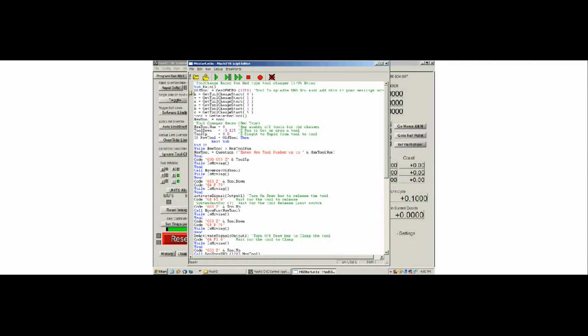As soon as that arrow goes past it, I can cursor over it, and old tool equals 4, so we know it's working, and I'll stop the flow of the program. So this gets the tool that's in the spindle, which is our old tool. I did old tool and new tool, and you'll see why in a bit. We also get our positions where the tool change was initiated, because I'm going to actually move the machine back to that position when we're all done our tool changes.